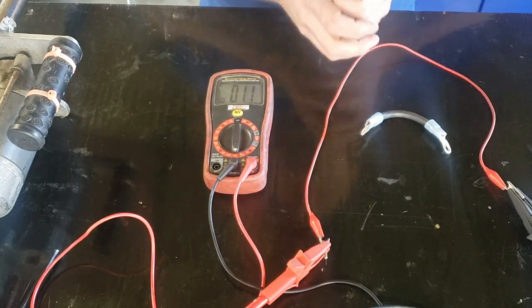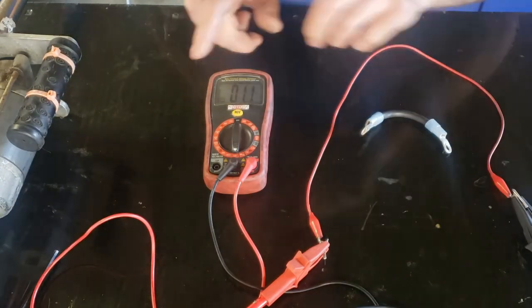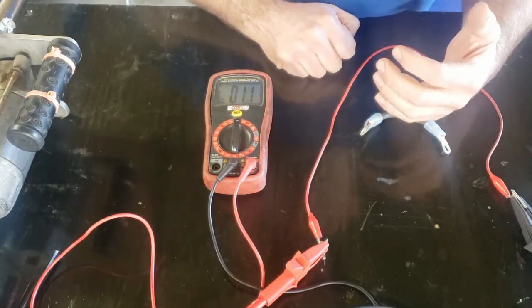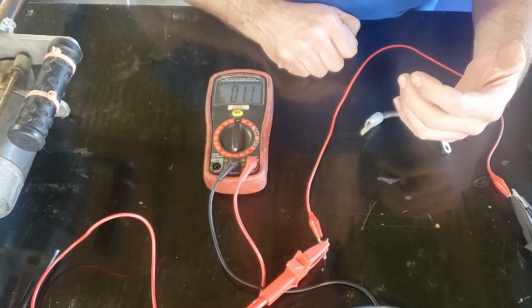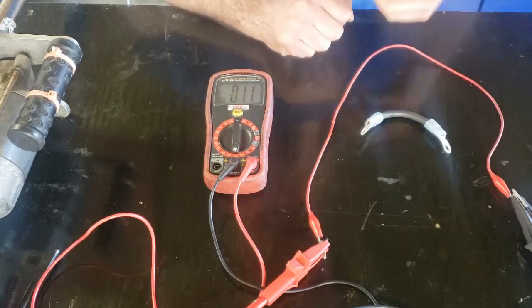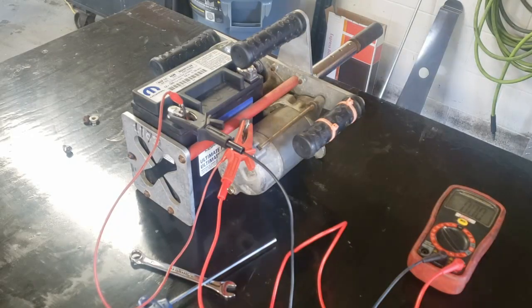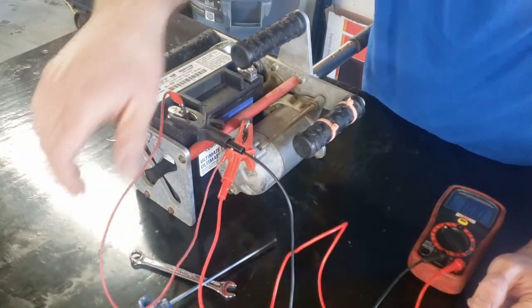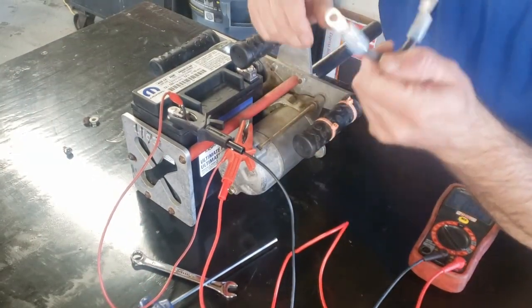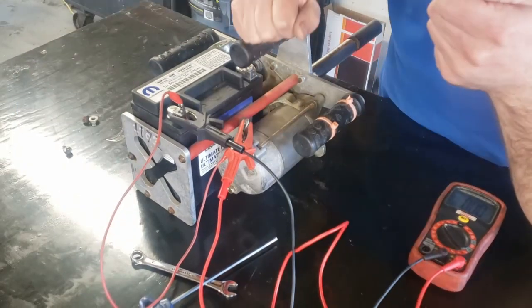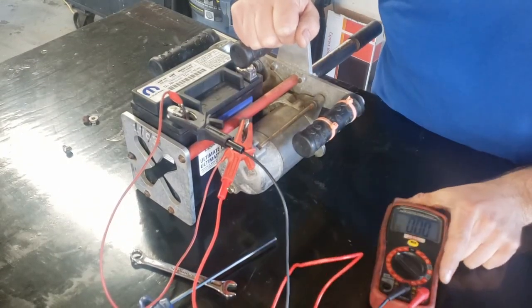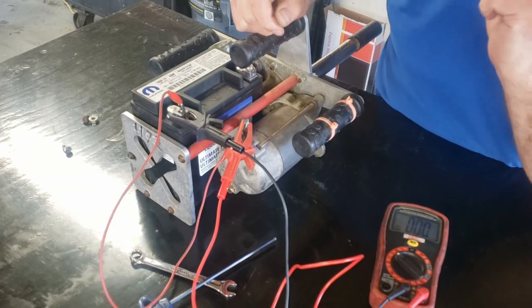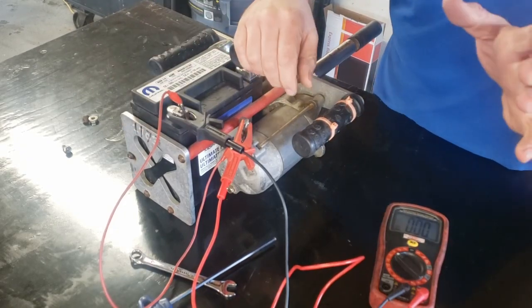But the question is, what's going to happen if I connect this jumper wire and try to spin this starter motor through this jumper wire? So let's look at what that actually looks like. Okay, for the sake of demonstration, I have taken my little 16 gauge jumper wire, I've replaced my battery cable that should be there with this 16 gauge jumper wire, and I now have my multimeter set up on both ends of that jumper wire, one end to the battery, one end to the starter motor.